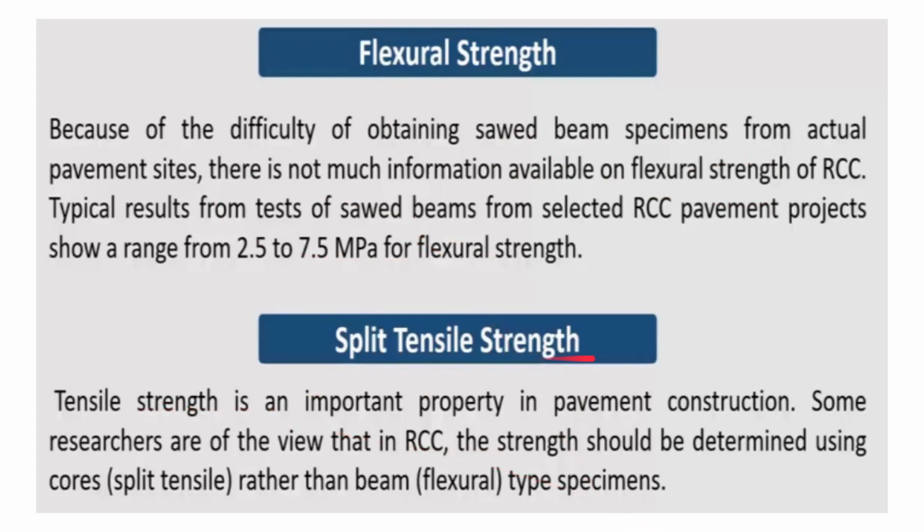And in the case of split tensile strength, the tensile strength is an important property in pavement construction. However, some researchers are of the view that in RCC, strength should be determined using split tensile rather than beam flexural type specimens, because of the problem of gathering sawed beam specimens from the actual pavement sites.